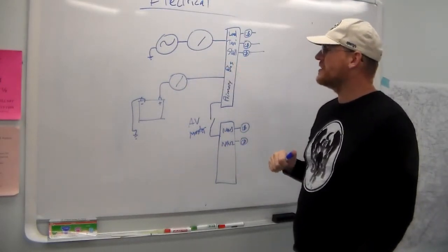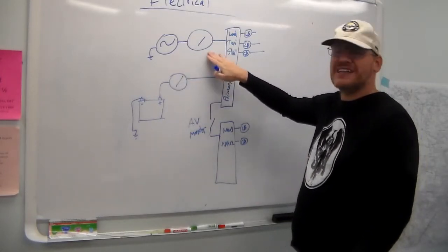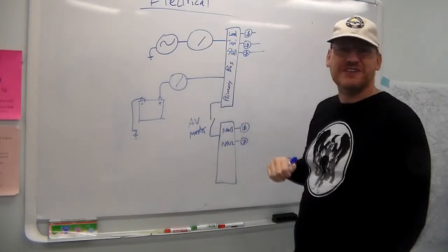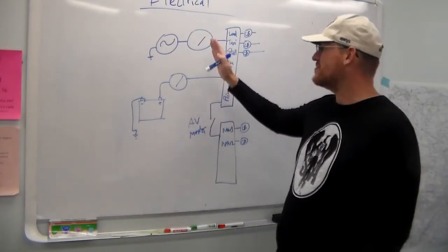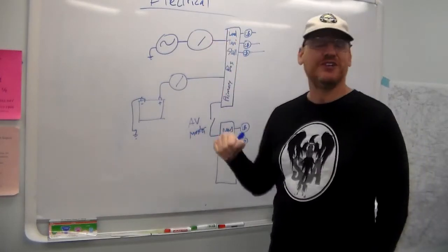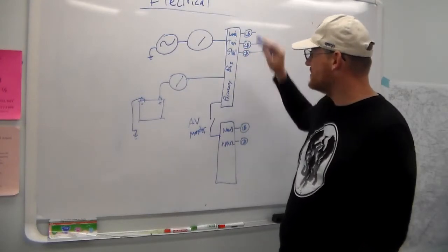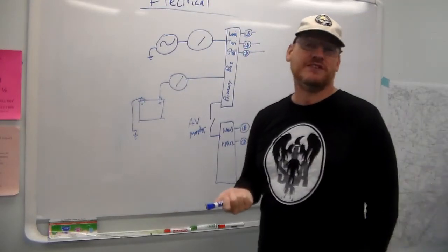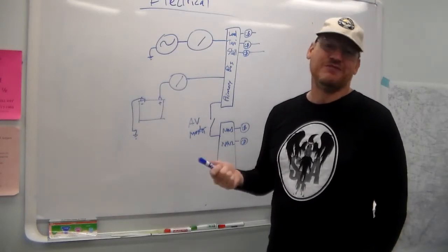In a typical aircraft, you have your alternator, and that's usually connected through some sort of meter, a load meter or a discharge meter. In this case, it'd be a load meter that shows how much current is coming from the alternator to the primary bus. So all a bus is basically a piece of metal, and you tap everything else off of it.